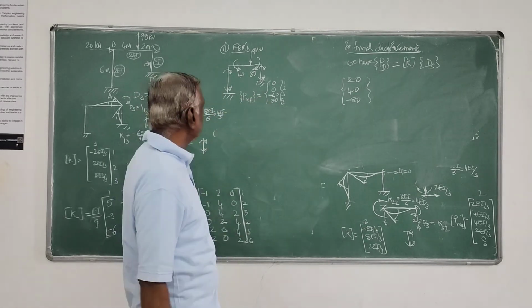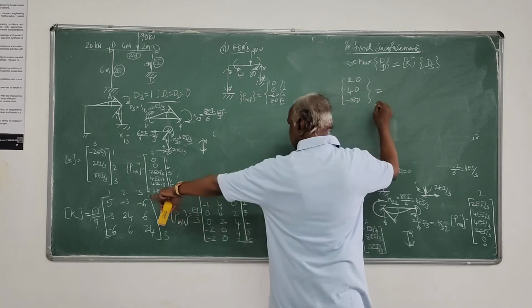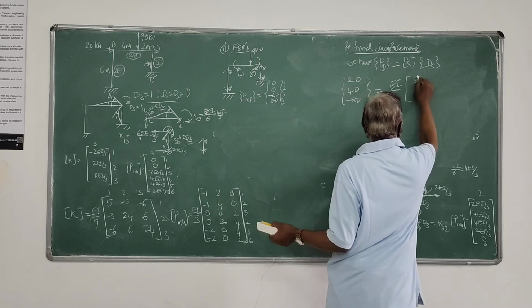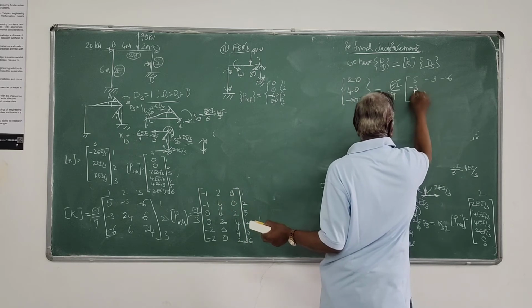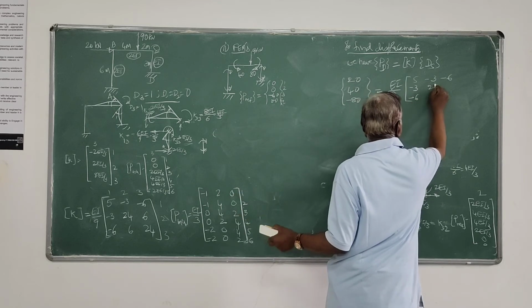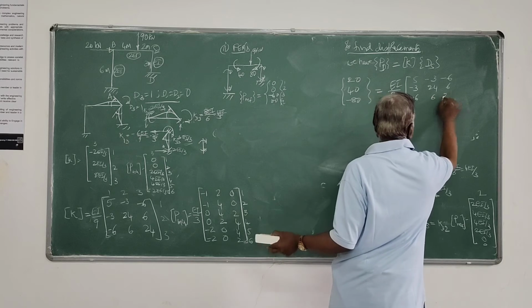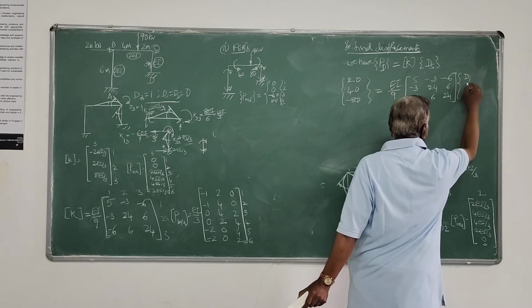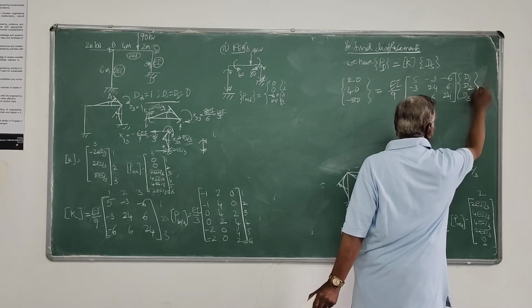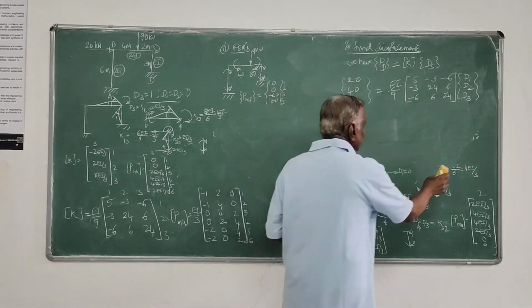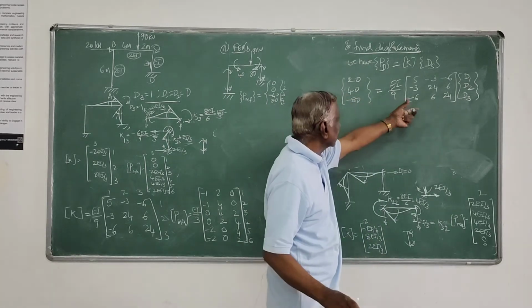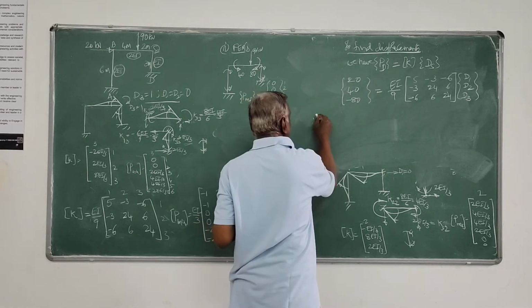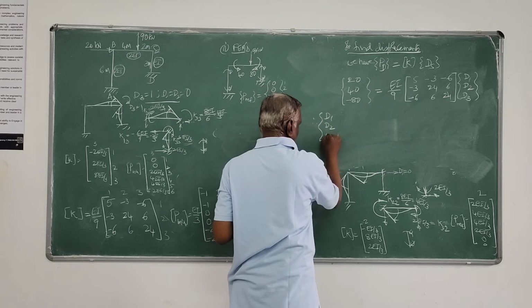Here we have generated that value. K is equal to EI by 9 into 5, minus 3, minus 6, and then we have 24, 6, 6, and 24. This is the K matrix. D is what we have to determine, that we have identified as D1, D2, and D3. So we have to find D. It is nothing but D1, D2, D3, which is the inverse of this matrix K multiplied by PD. Therefore, this is a simple calculation, the last two steps.